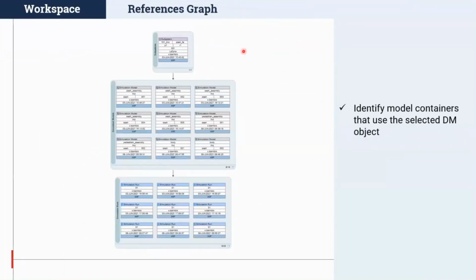Now, regarding the lifecycle graph and the reference graph, we have identified the model containers that use the selected DM object. The lifecycle graph has been enhanced so that for a particular subsystem, the user can not only show the simulation models that consist of this subsystem, but also get further references in a graphical manner for all the simulation runs that are referenced by those simulation models.